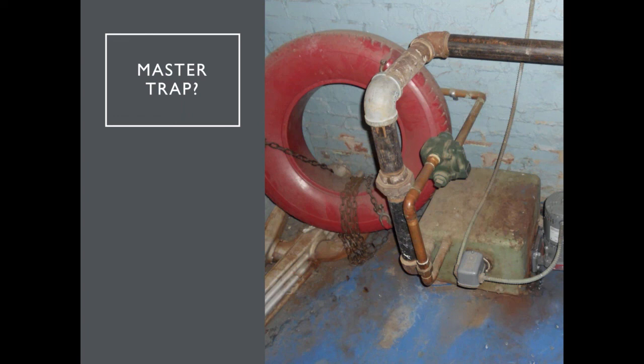ASME CSD-1 recommends and requires, if you're using a probe type low water cutoff, a push button to test it. So when I'm blowing down a hydronic boiler, I will do it maybe once every month or two. On a steam boiler, McDonnell Miller recommends once a week for low pressure steam, and they recommend daily if it's high pressure steam.